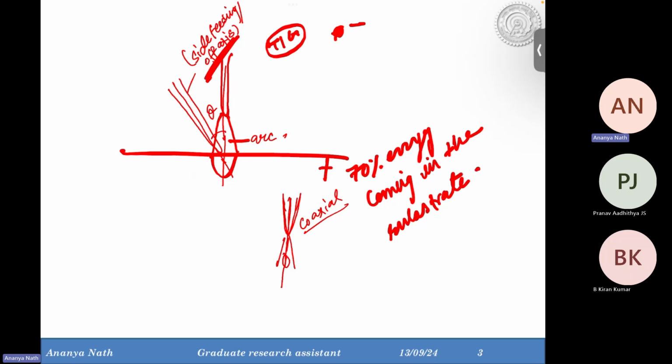Tungsten material is used in the electrode, and this is for DC, and if you are using AC, then it is well and good. Again, as I said, aluminum is welded or used in additive manufacturing with the AC type of WAM process.